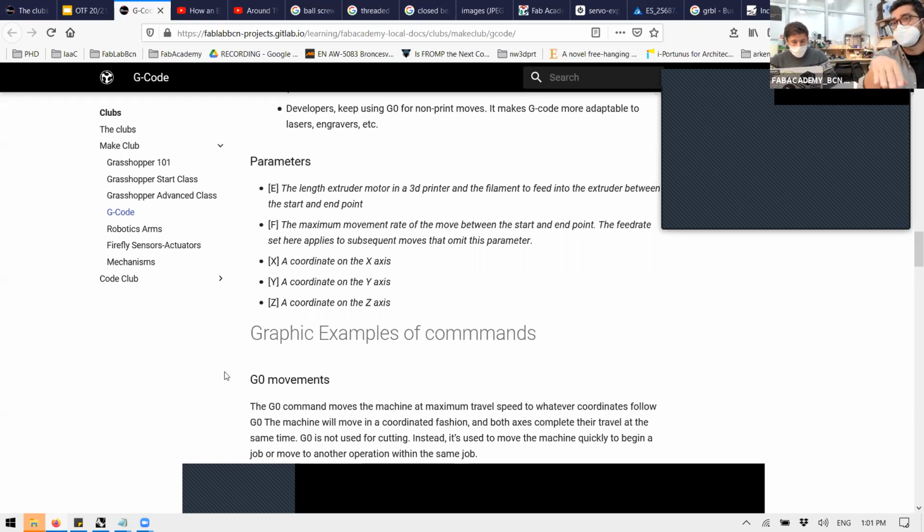If you cut for 1 hour, that's fine. But if you're making a production of 14 hours and you need to go to the restroom and your machine somehow doesn't have a pause, you can send a command in live to pause. That is G4 P500, which is a pause for half a second, for example. It's really important to know how to use the commands because, first, you can debug what happened, and second, you can upgrade things and change them. You can introduce changes on the go. That is a really important thing.